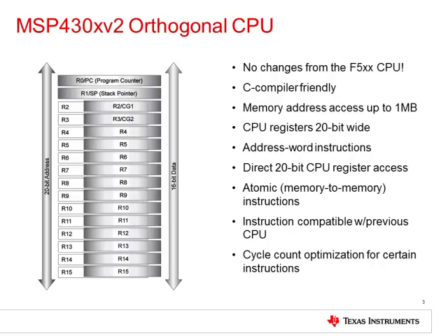The MSP430X RISC CPU includes other features such as an orthogonal architecture, full register access including program counter, status register, and stack pointer, single cycle register operations, a large register file that reduces fetches to memory, a 20-bit address bus that allows direct access and branching throughout the entire memory range without paging, a 16-bit data bus that allows direct manipulation of word-wide arguments, a constant generator that provides the 6 most often used immediate values and reduces code size, direct memory-to-memory transfers without intermediate register holding, and byte, word, and 20-bit addressing.